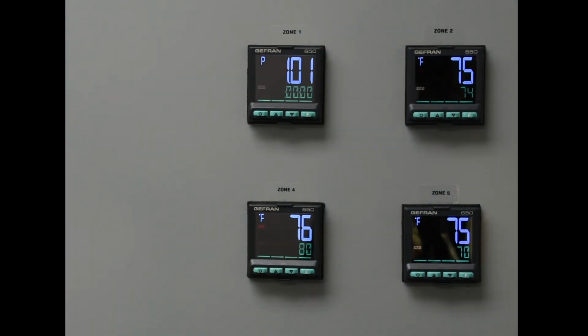It is important to remember the following about programming. Pressing the F key is required to accept changes to parameters. While a program is running, pressing the down arrow will put a program on hold. Pressing the up and down arrows together will stop a program. Even though a program may not be running, the program number and the step will show on the display if the control module is in the program mode.